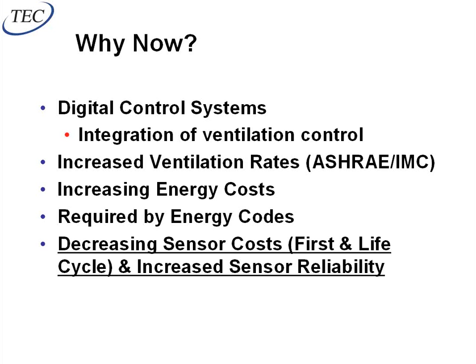So in 2000, nobody wanted to hear what I had to say. By 2006, it became a pretty popular topic that everybody wanted to talk to me about. And unfortunately, I don't sell CO2 sensors anymore. But when I used to, it would have been much more fun if people accepted it. Energy costs have increased and probably will continue to increase for quite some time. Energy codes play a big factor, like we said. Now, in some cases, the energy code actually spells out that you have to do DCV, and you don't have a choice if it's a densely occupied space.